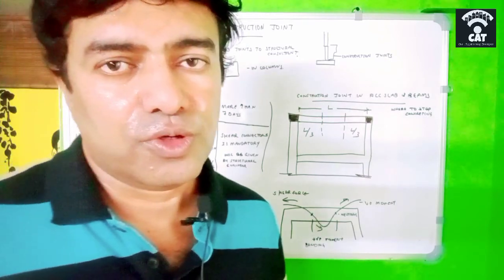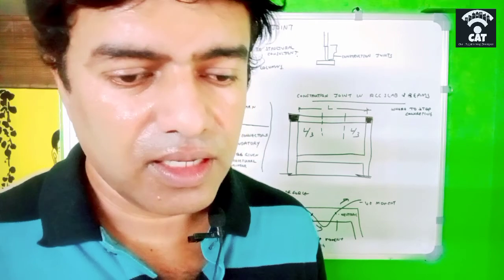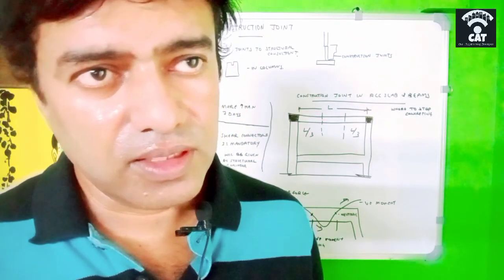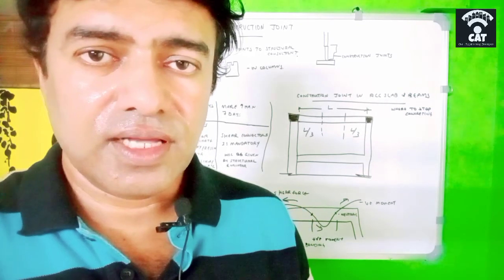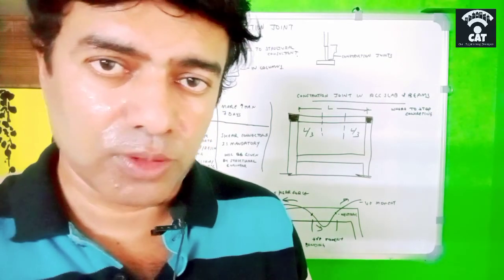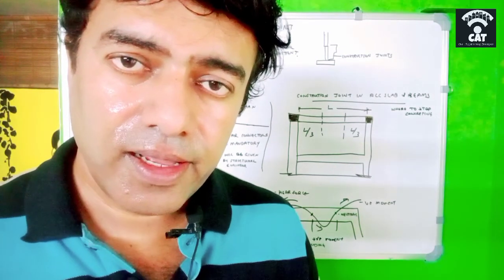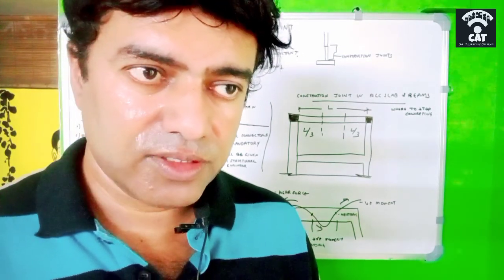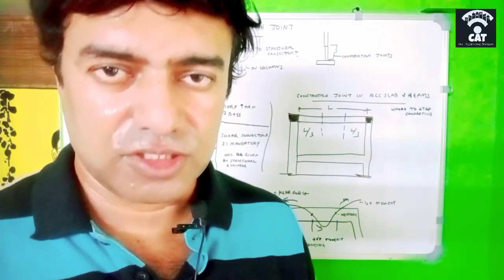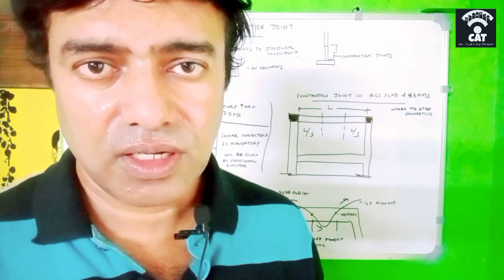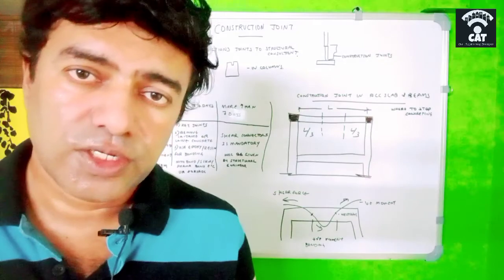Laitance means, after the vibrations have been done in the concrete, the small powder-like cement will come up to the surface, and it may be there on the top surface. We have to clean that, remove that, or just remove the loose concrete which is available there. Make it clean, and then we can go for the construction joint with the next ongoing concrete work, if we can do these things within 12 hours.